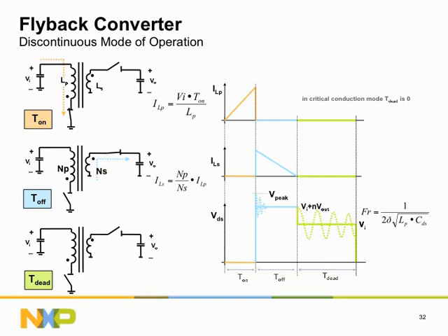After the secondary stroke, there is another ringing waveform which is caused by the primary inductance, LP, and the capacitance of the primary switch, CDS. This ringing leads to a sequence of peaks and valleys during the dead time. In a smart switching strategy, the occurrence of valleys can be used to reduce power loss and switching noise. We will go into the details in the next course module.